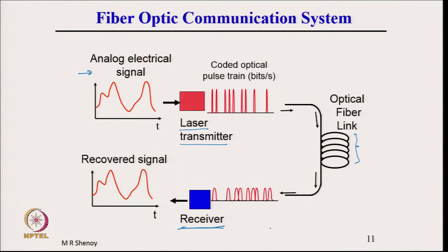What we note here is the input pulses are sharp and pulses of large amplitude. At the output, we see that the pulse amplitude has dropped and the pulses have become wider. They are completely separated here. For example, this is a 1, this is a 1, this is a 0, this is a 1, there are zeros, then 1, 1, 0, but we see that the ones are very, very close, they tend to overlap. So, this is deliberately shown because the fiber link has two important characteristics. One is loss and the second is dispersion. So, dispersion.